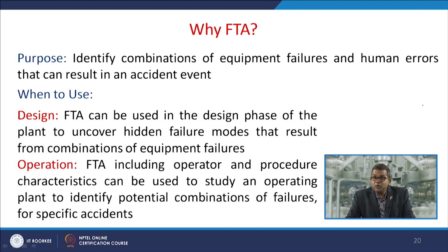Now the question arises, okay, we know why we are using fault tree analysis, but when to use it? There are a couple of options. One is the design mode, where fault tree analysis can be used in the design phase of the plant to uncover hidden failure modes that result from combinations of equipment failure. Another is with respect to operation. Fault tree analysis including operator and procedure characteristics can be used to study an operating plant to identify the potential combinations of failure for specific accidents.